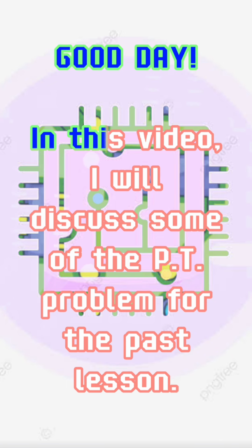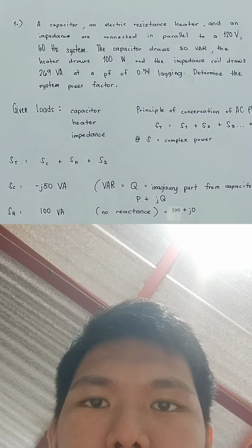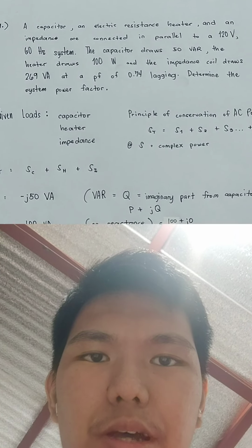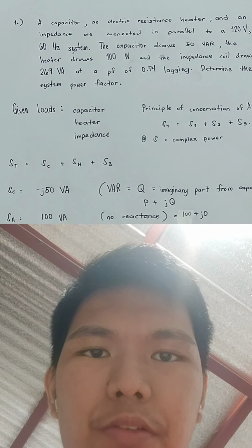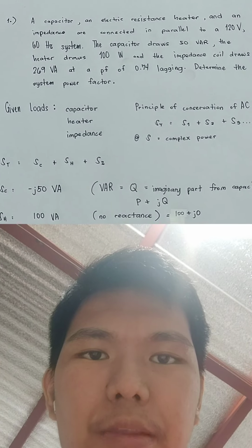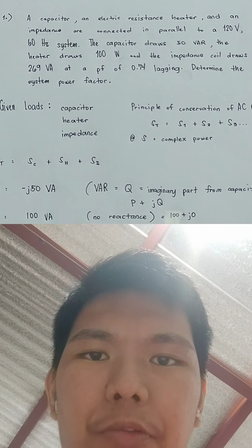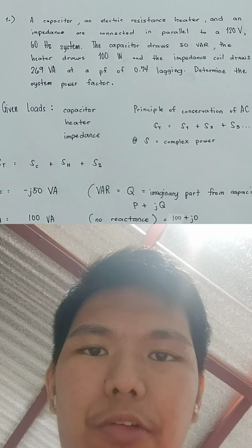Good day. In this video, I will discuss some of the PT problems, fourth pass. For number 1, a capacitor, an electric resistance heater, and an impedance are connected in parallel to a 120 volt 60 Hz system. The capacitor draws 50 var, the heater draws 100 watts, and the impedance coil draws 269 volt-amperes at a power factor of 0.74 lagging. Determine the system power factor.